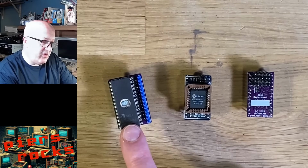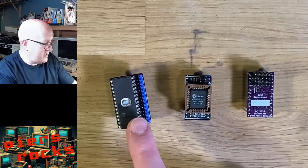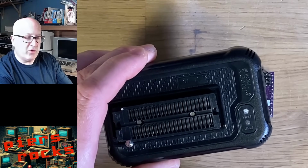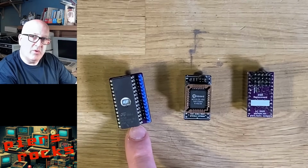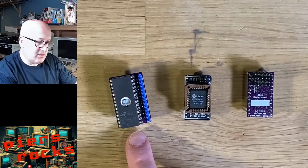You then have to put this into a UV light source for a couple of minutes to erase it. Then you need to put it in the programmer, which will cost you $40 or $50. Then you need to reinstall the chip back in the replacement board and stick it back in your host. That's going to take you 5 or 10 minutes to do.